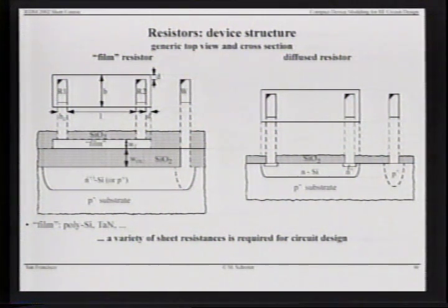next slide. On the next slide here, on the right-hand side, the classical diffused resistor, a very cheap solution in many processes, sometimes preferred to offer. And this is the solution usually designers prefer more. This is a film resistor, I would like to call it. The film could be polysilicon or another material here. And the isolation of this one, as you can see, is better because it has silicon dioxide here compared to, in this case, junction capacitance.